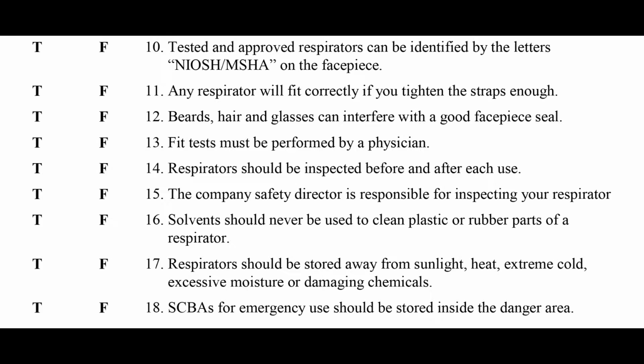True or false? Number 12, beards, hair, and glasses can interfere with a good facepiece seal. That's true. Number 13, true or false? Fit tests must be performed by a physician. That's false. Fit tests can be performed by a qualified employee or supervisor. Fit checks can be performed by trained users. Number 14, true or false? Respirators should be inspected before and after each use.